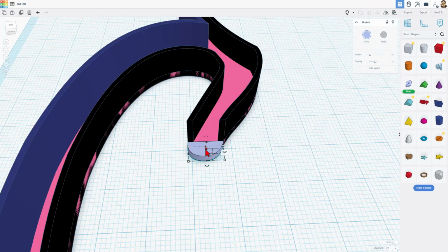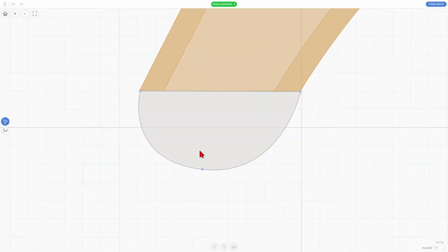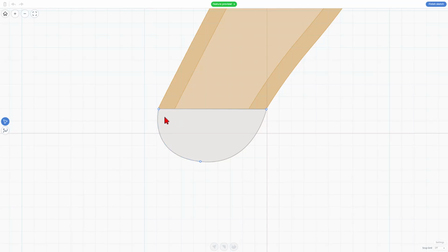First, I'm going to do Control D. So I've got 2 of them there, and I'm going to double click the sketch. The cool thing about this is now I can go to the add points, and I want to add a point here, and here, and here, and then I can pull, and then I can switch to the modify mode. Don't forget you do have to switch, otherwise it'll delete it. And we can bring this out here and create our 2 millimeter walls.